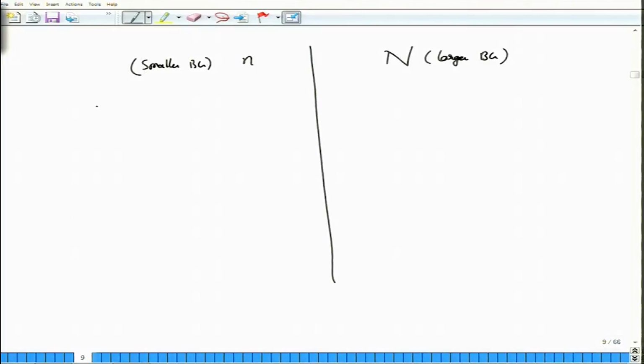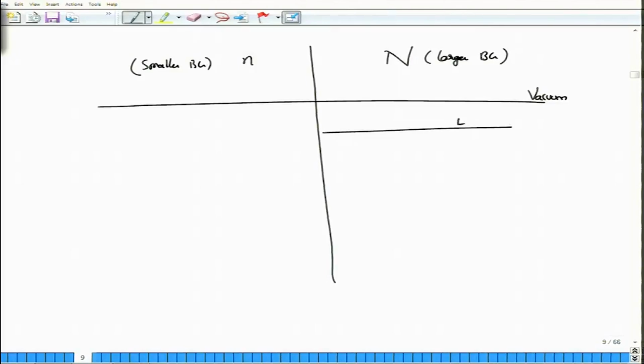But we will also assume that corresponding to the vacuum level, okay, the electron affinity, which is where we had located the conduction band over here, so I should not write it very close to the junction because the property will change. So, I am going to write here, and this would be my conduction band, which I would call EC2. Of course, this distance between the vacuum level and the top of the conduction band is the affinity chi 2. Okay. The smaller the affinity, the smaller the energy required for the electrons to be removed from that particular material. Please keep that in mind, that is very important.